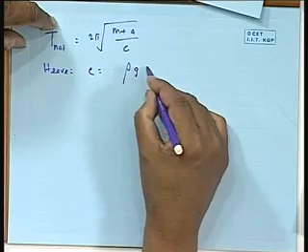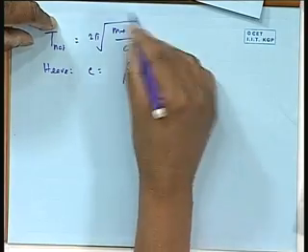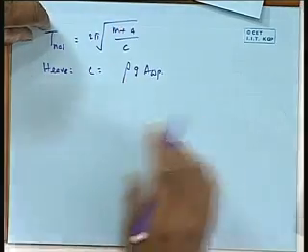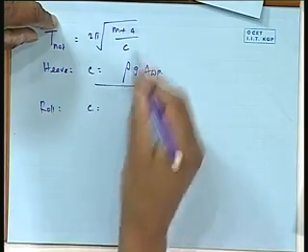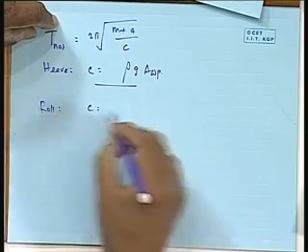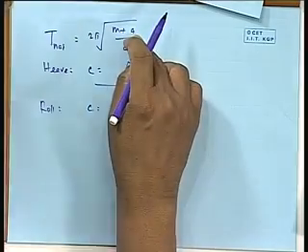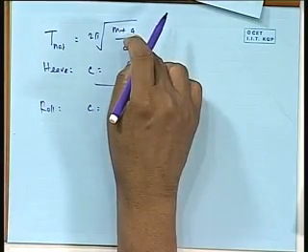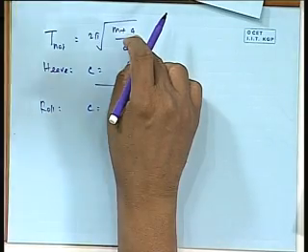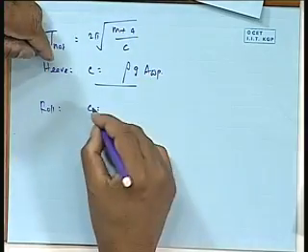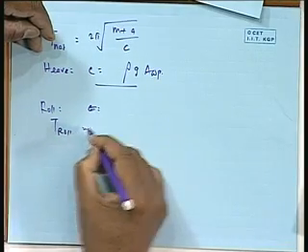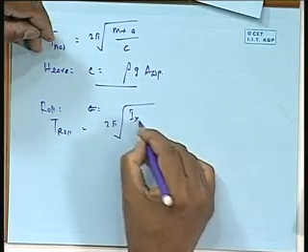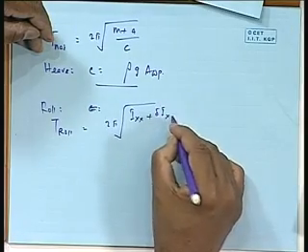Now, for heave, the C is given by rho into g into A_WP, and this is m plus a, mass plus added mass. Now, for roll, this m plus a will be replaced by Ixx plus added Ixx, because it is now the rigid body moment of inertia. So T roll is 2 pi root of Ixx plus delta Ixx. What is Ixx?